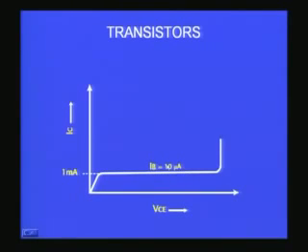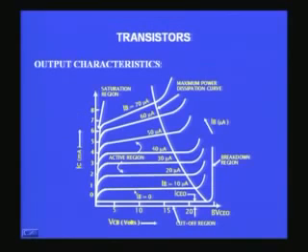If you go for different base currents, you would find higher base current, for example, 20 microampere if I take, you would find this saturation comes at a later stage. That is what is shown in the graph here on the screen. This is for one current IB equal to 10 microampere, this is for the second current IB equal to 20 microamperes, and this for 30 microampere. So, as you keep on increasing the current, the graph will go according to what is shown here.